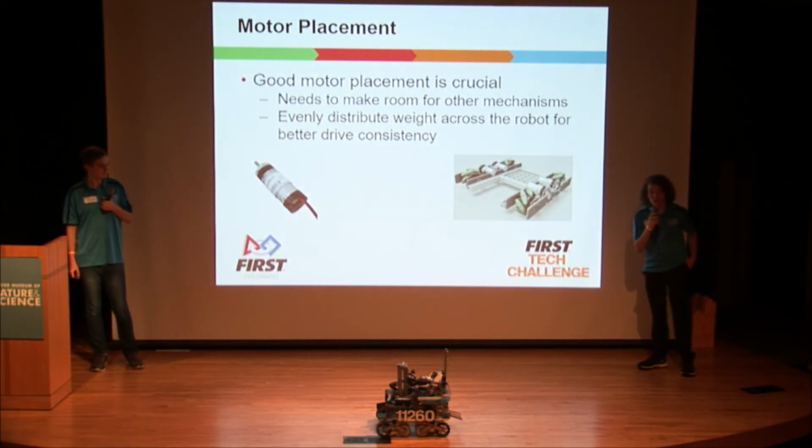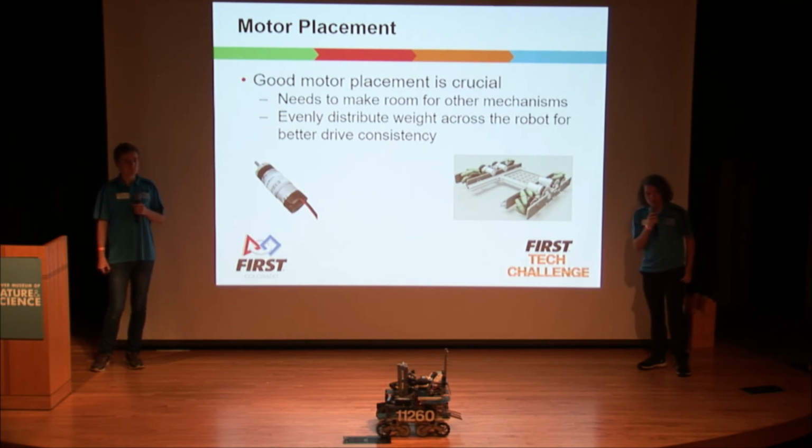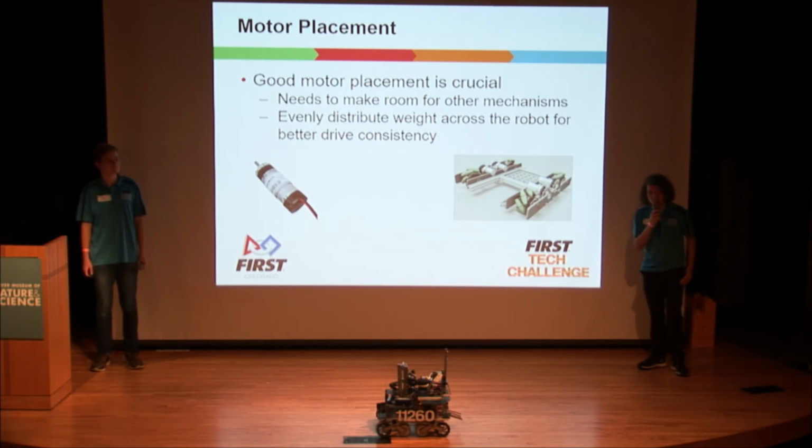So when you're building your chassis, you want to make sure that your motor placement is good so that it leaves room in the center of your robot for mechanisms such as an intake, and it evenly distributes weight across your robot.